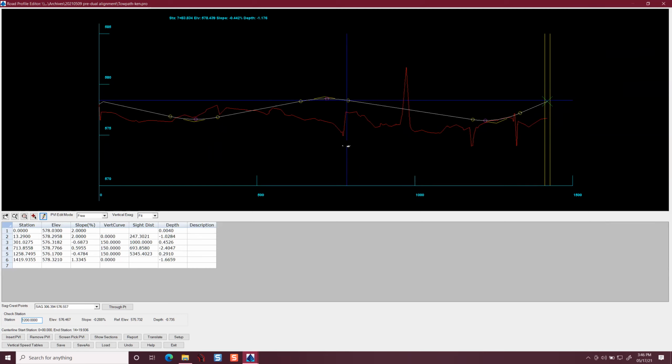I'm going to go ahead and let it do what it does and clip off that surface. That's fine with me because I'll just rebuild the surface anyway. I can pick that part up. I've got to dress that intersection up anyway. I really don't want to get into trying to make the dummy road, to model it as an intersection, because then I got to treat that somewhere else.